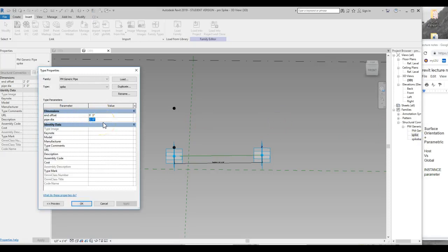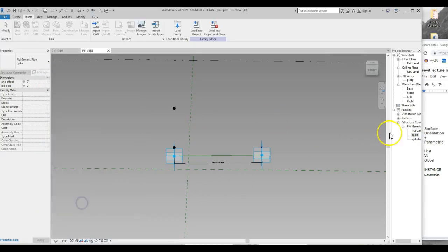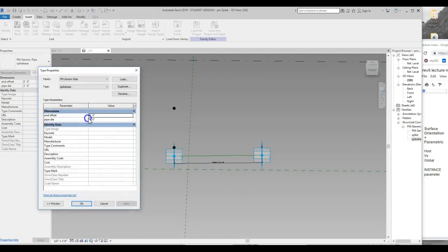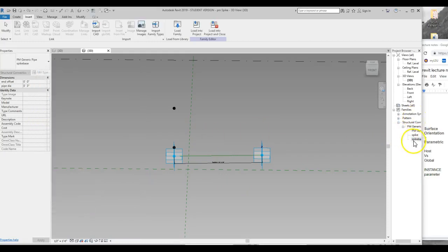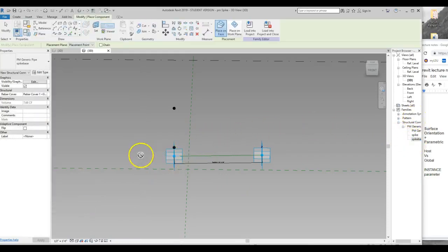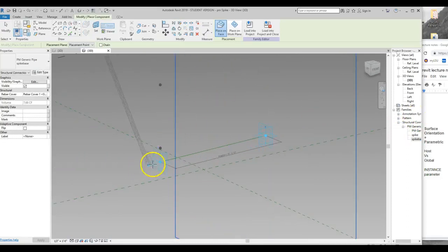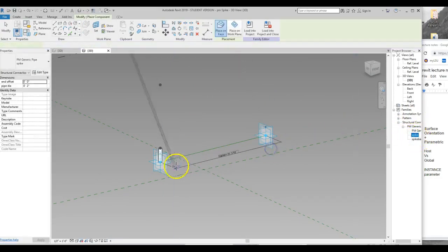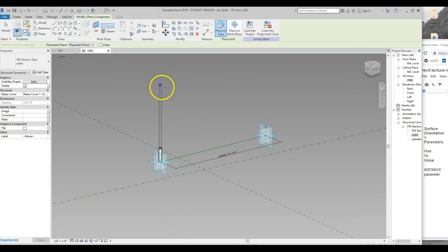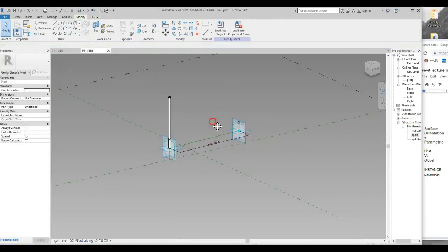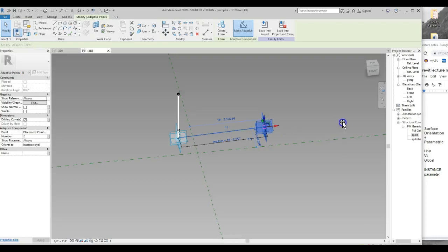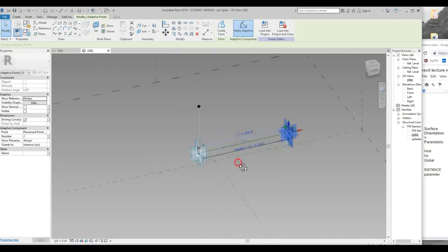Oh, that's 3 feet. I don't need 3 feet, 3 inches. This I'm going to do 2 inches. Let's go back into that. Let's make this 3 inches. Okay, so now let's grab that spike base, two. Let's grab the spike, 1, 2. Okay, let's see if it works. Yep, that spike's moving, right? Because the adaptive pipe is adapting to that.